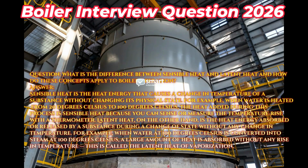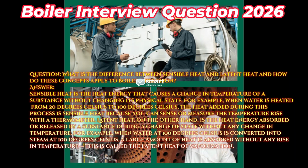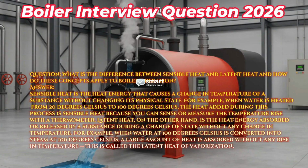Question: what is the difference between sensible heat and latent heat, and how do these concepts apply to boiler operation? Answer: sensible heat is the heat energy that causes a change in temperature of a substance without changing its physical state. For example, when water is heated from 20 degrees Celsius to 100 degrees Celsius, the heat added during this process is sensible heat because you can sense or measure the temperature rise with a thermometer.